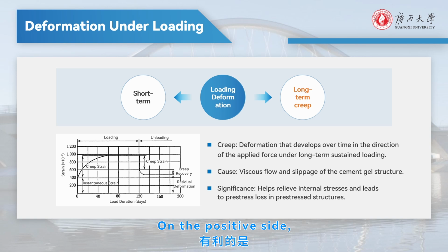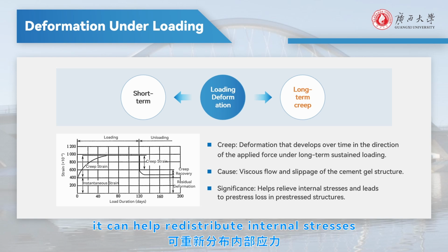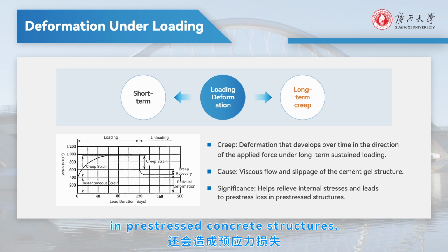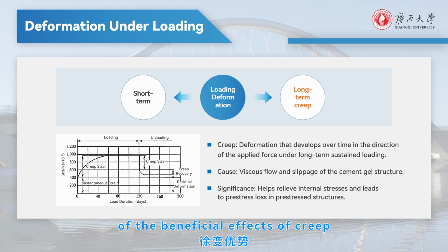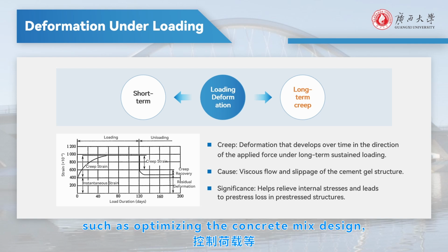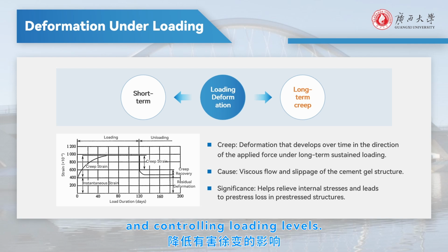On the positive side, it can help redistribute internal stresses and relieve stress concentrations. On the negative side, it can increase member deflection, lead to excessive deformation, and cause pre-stress loss in pre-stressed concrete structures. Therefore, in engineering practice, it is important to make proper use of the beneficial effects of creep while minimizing its harmful impact through measures such as optimizing the concrete mix design, improving curing conditions, and controlling loading levels.